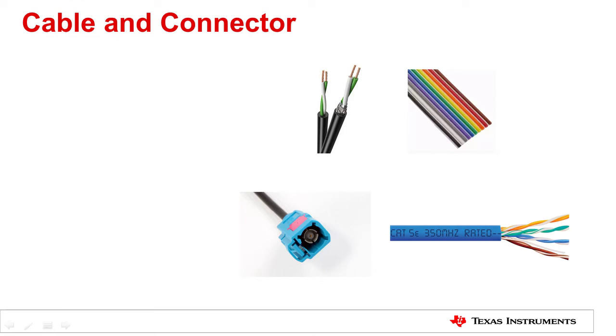After part selection, let's look at cables and connectors. LVDS only defines how signals get transferred. It should be independent from cable and connectors. But that's not the case in the real world, because the performance of the cable and connector will affect the performance of LVDS technology. When considering what cable and connectors to use, here are a few things we should keep